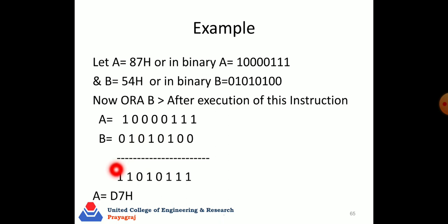So if we write it in hexadecimal, here 8421. So 8 plus 4 is 12, 12 OR 1 is 13. So 13 is written as D, and the other nibble is 0. 8421, so 4 plus 2 plus 1 is 7. So D7. That is, the result is D7.